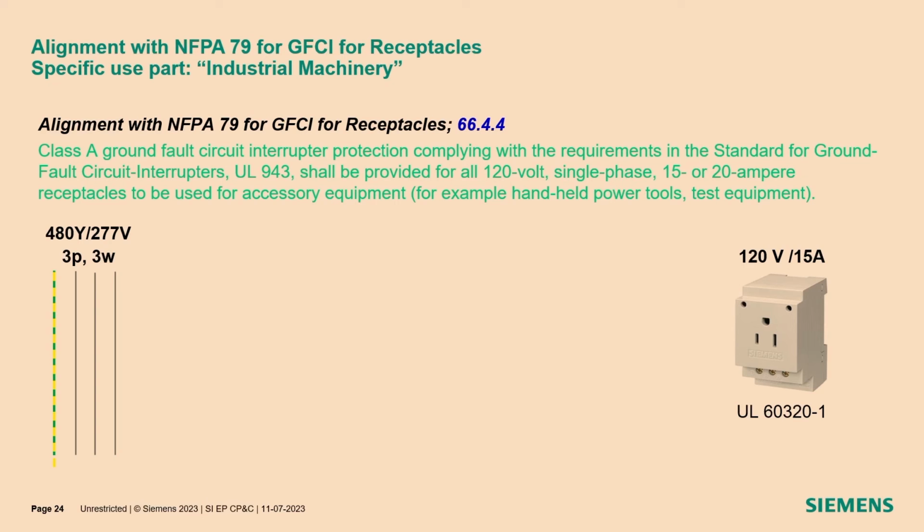The maximum rated current is 15 amps. It fits the American wire gauge of 14. It's perfect here, and this is the only thing I can recommend. How do we bring this now to the power lines of 480 volts?